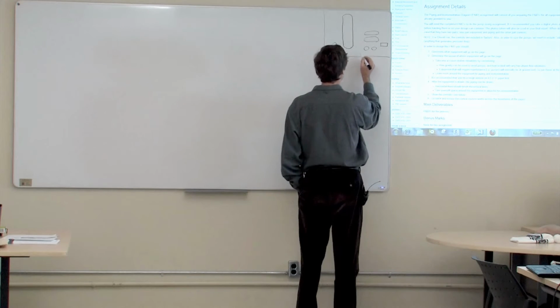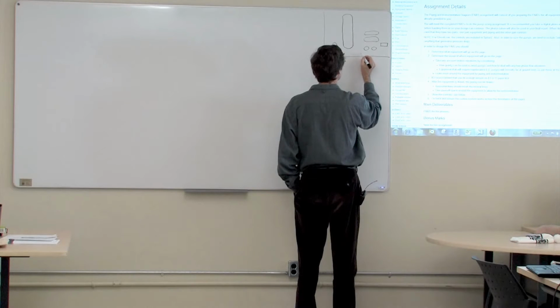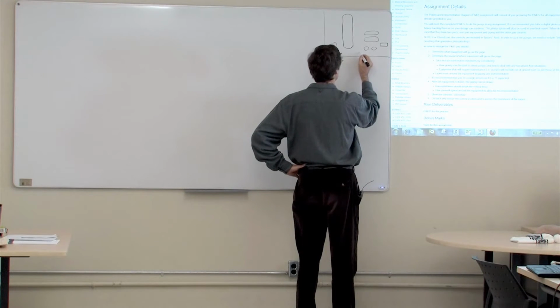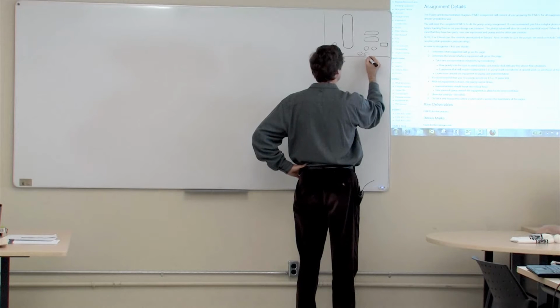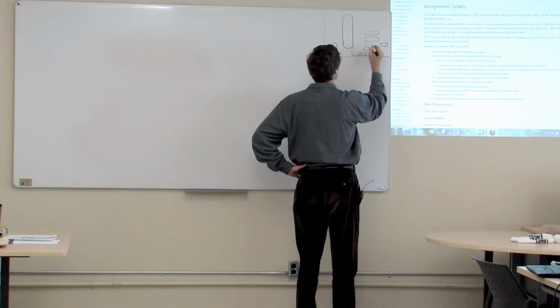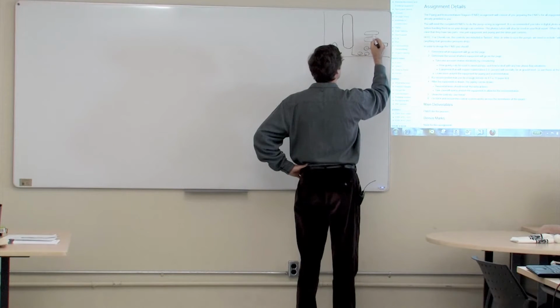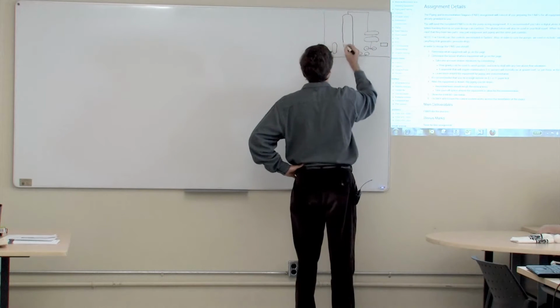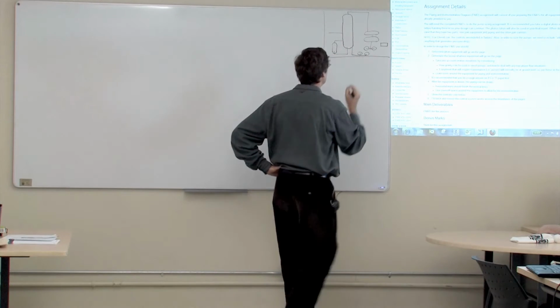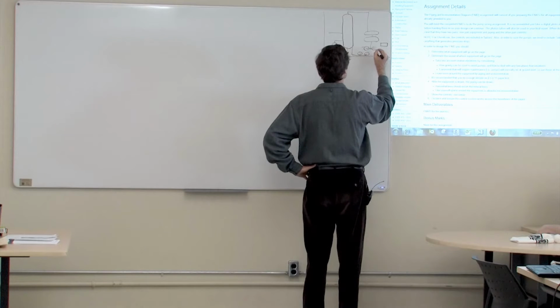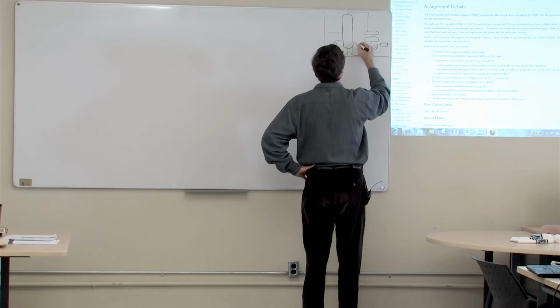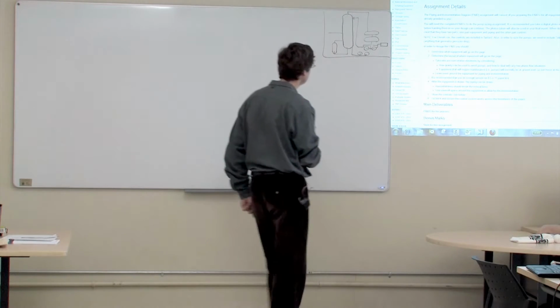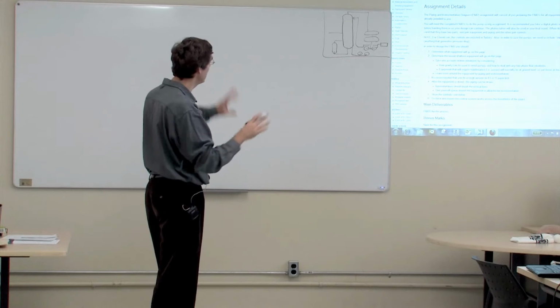And there's a good chance that I'm going to need some bottoms pumps to send this material off to the waste treatment. So I'm going to show those there roughly. And so it's going to look kind of like this. There, off to there, like that. And my reflux pumps, one's going to go off to there. And my reflux is going to have to go up into here. Okay, so that gives me a sense of how I want to lay the drawing out,